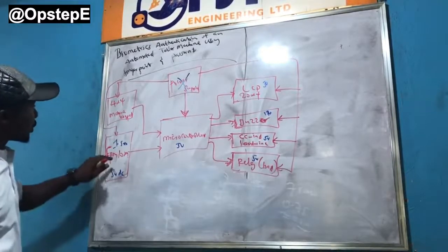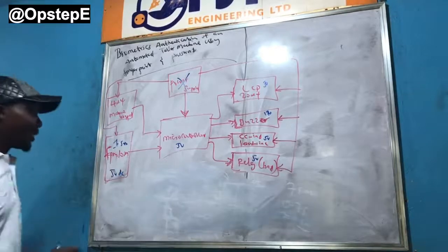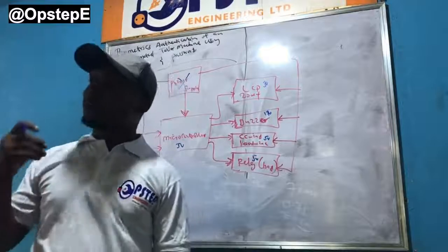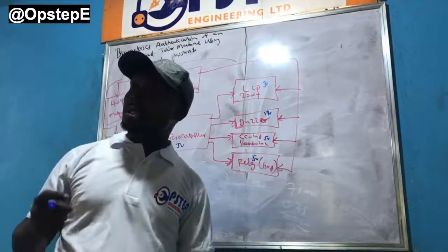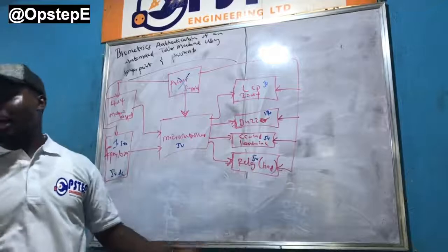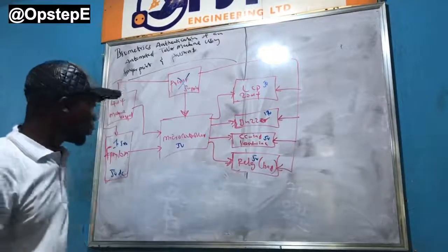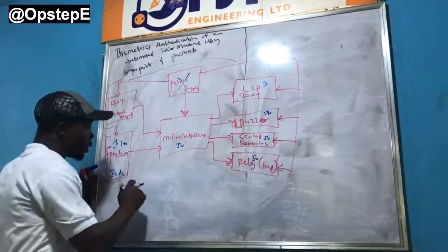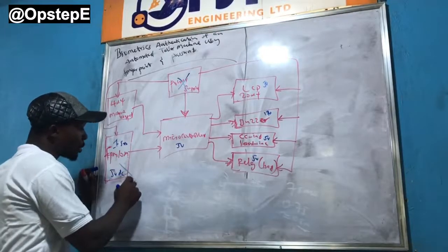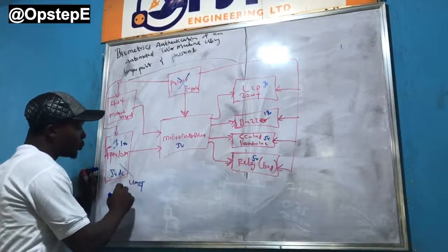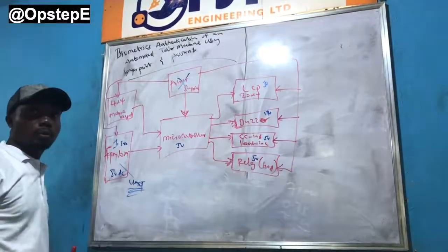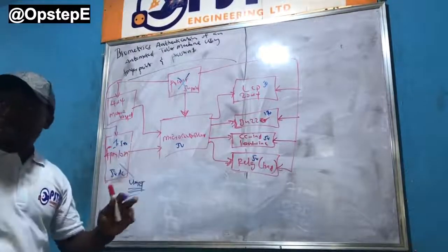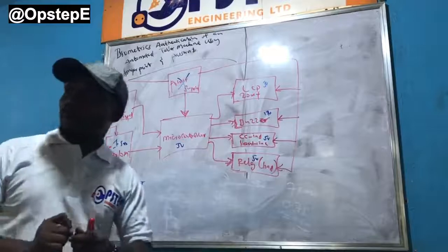Quickly, the fingerprint module. If you get the data sheet, like I said, when you pick up a sensor or any module for that matter, before you use it, visit the manufacturer's data sheet. Go online, use Google, find it. From all that we gathered, it communicates using UART. What that means is that it will only be connected to the UART pins of the microcontroller.